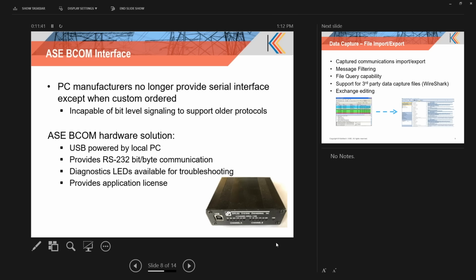debug and troubleshooting, because in certain scenarios, even though you've defined a configuration for testing and it appears that you're actually sending information to a destination device, without LEDs it's very challenging to determine whether or not the message was received. And these LEDs are pretty handy in identifying communication setup scenarios where a parameter may not have been defined correctly, or it can support a conclusion where a device received a perfectly defined message and it's not responding accordingly.